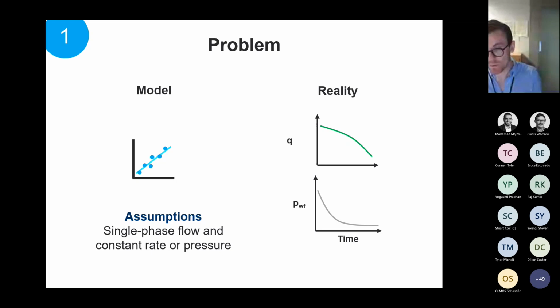And we typically drop below the saturation pressure, so we're dealing with multi-phase flow effects as well. And even if you're kind of single phase, you're still producing a lot of water and potentially oil, or vice versa for a gas. So even then, you're dealing with multi-phase flow. So the way to solve this is to do RTA with something that can actually account for superposition and multi-phase flow effects at the same time.